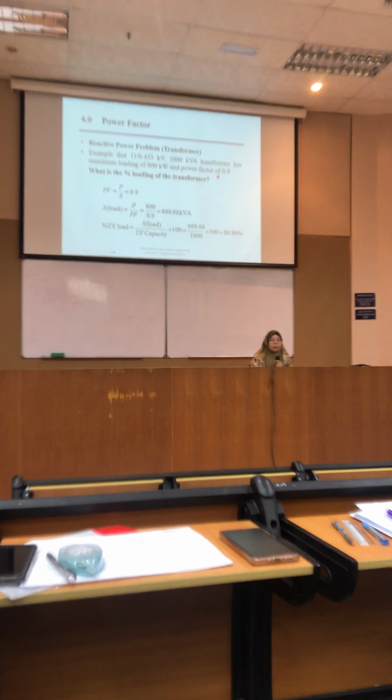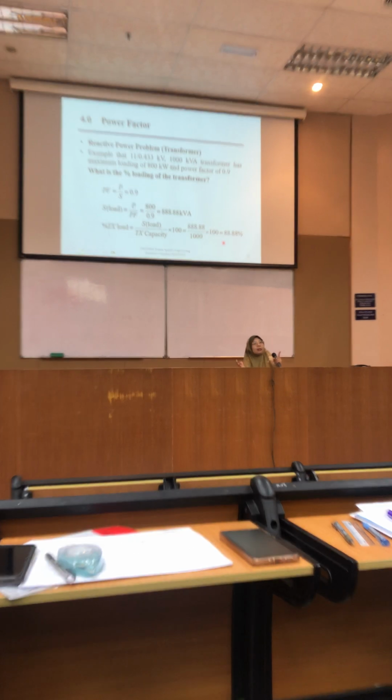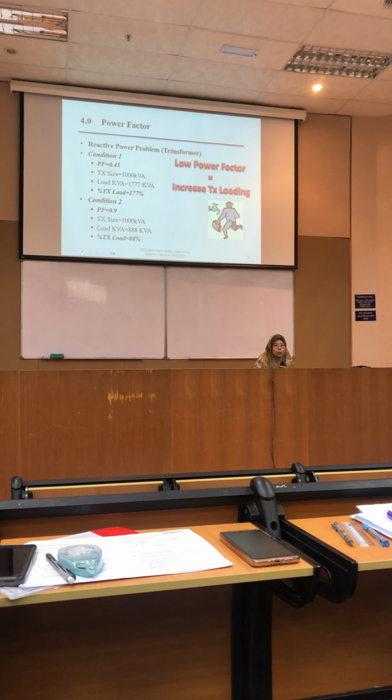What will happen if the power factor is 0.9? The loading is 88% of the transformer, so the capacity is 100 and the transformer loading is 88%. So reactive power on the transformer, a low power factor, increases the transformer loading.